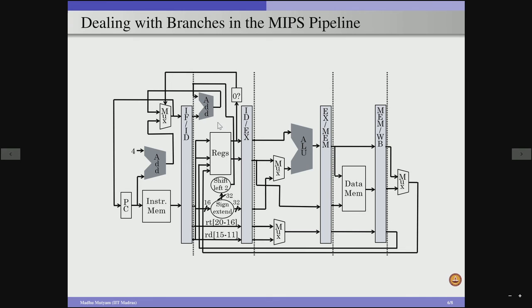2nd stage itself. Previously we were using this ALU to compute the branch target address and also the test condition for the branch, but now we are adding a separate hardware component in the 2nd stage, so that our branch outcome and the branch target will be completed in the 2nd stage. But the trade off is we are going to incur extra hardware overhead associated with an adder, but the advantage is we are going to resolve the branches quickly.